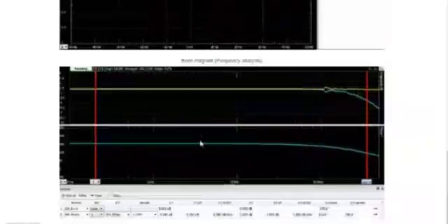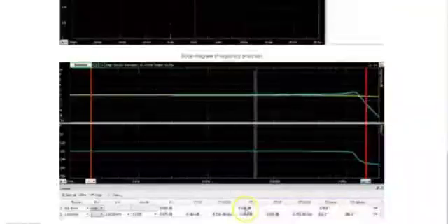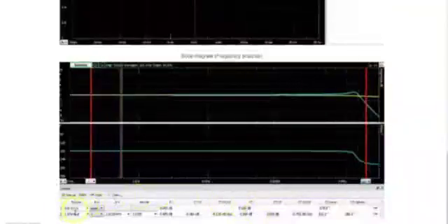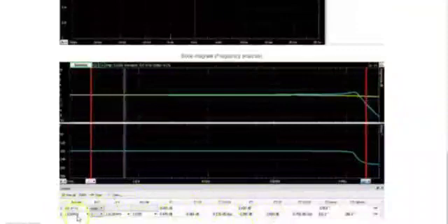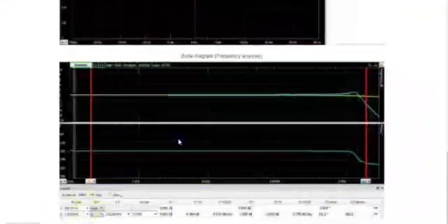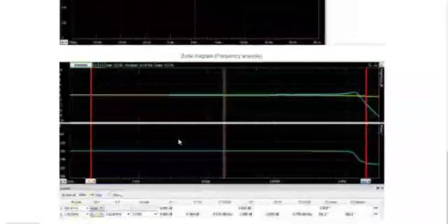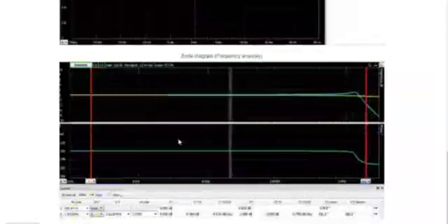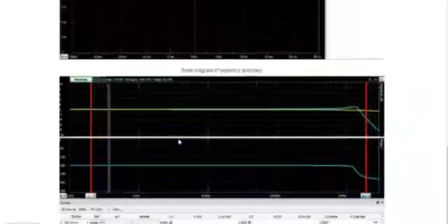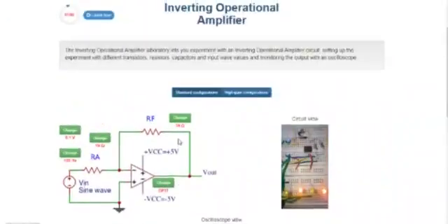The above process is carried out for another op-amp OP37 with better performance parameters. In the first case with Ra equal to 1 kΩ and Rf 10 kΩ, the gain and frequency are 20.02 dB and 202.04 Hz respectively, and the 3 dB bandwidth is increased to 1.754 MHz. This shows that the op-amp OP37 with larger open-loop gain has better bandwidth compared to that of UA741. Like this, the analysis can be done for other combinations of resistors, signal amplitude and frequency.